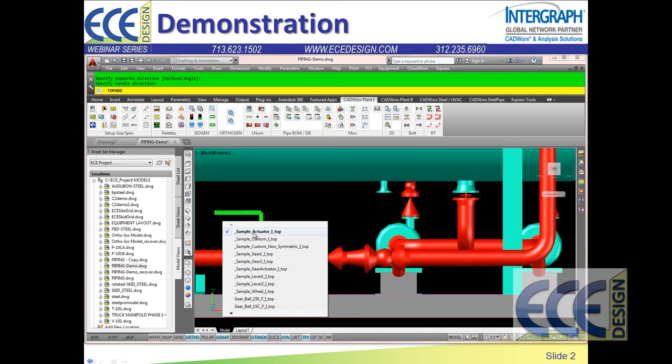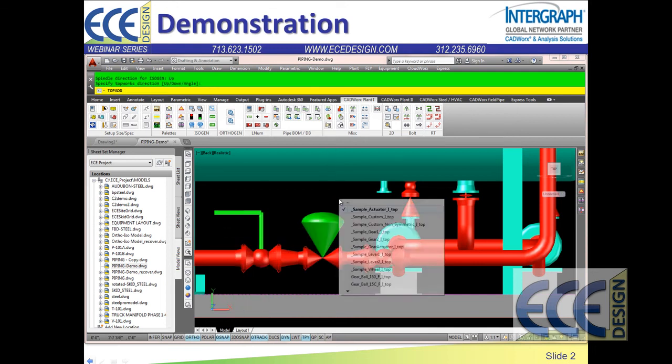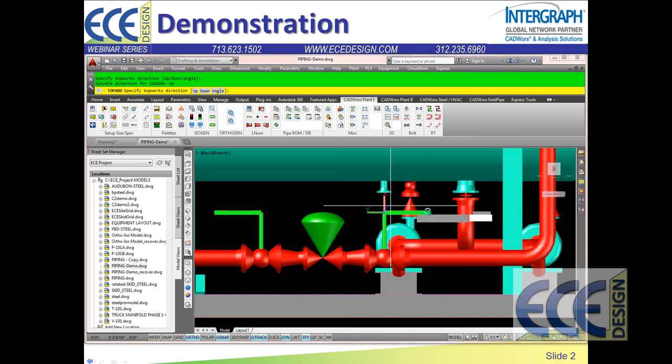The second one is my control valve, so I'll select an actuator for it, and then the third is the other block valve, so I'm going to go up and to the right with that one. One reason I wanted to do this is so I can make sure I've got clearance, like for this saddle, and that my lever doesn't hit the standpipe, etc.